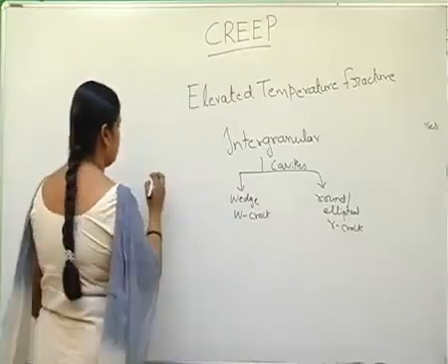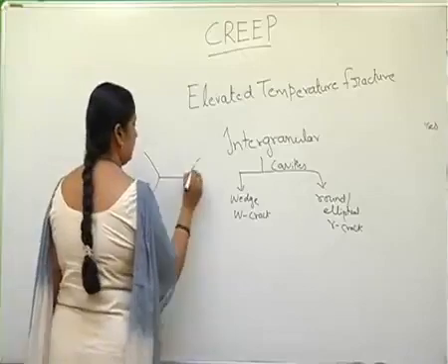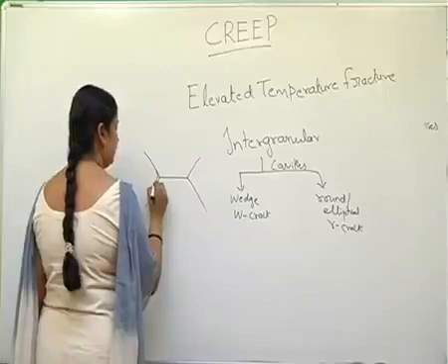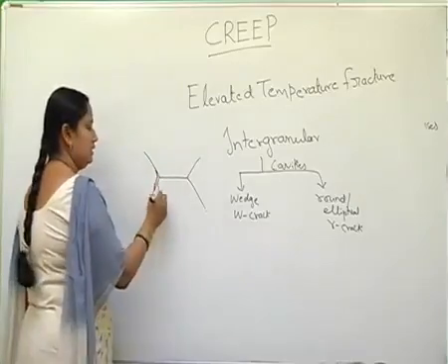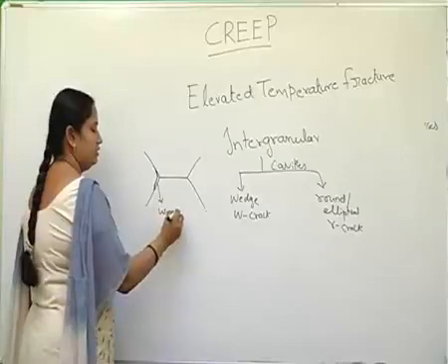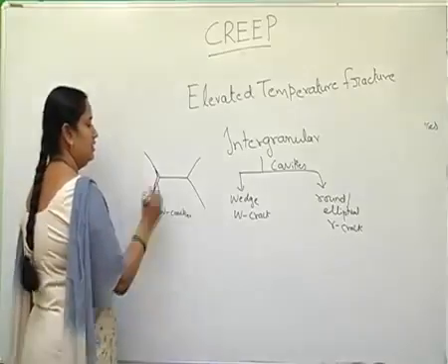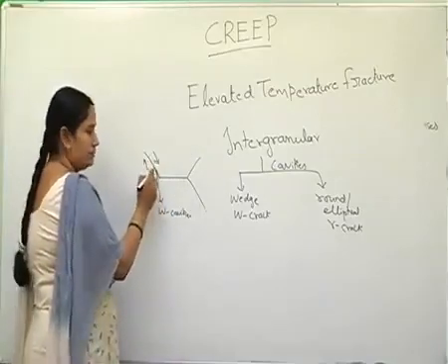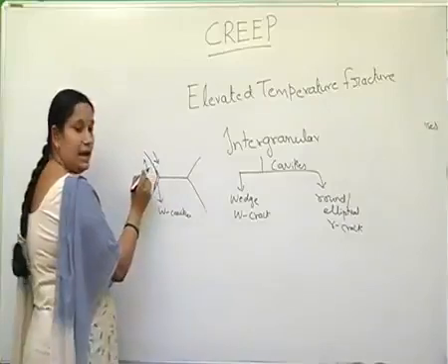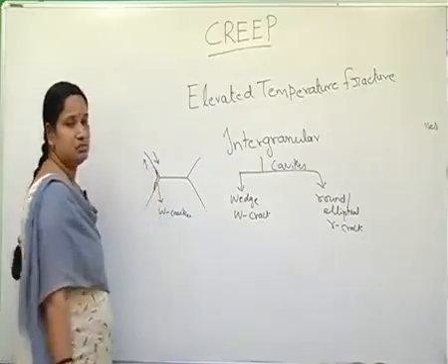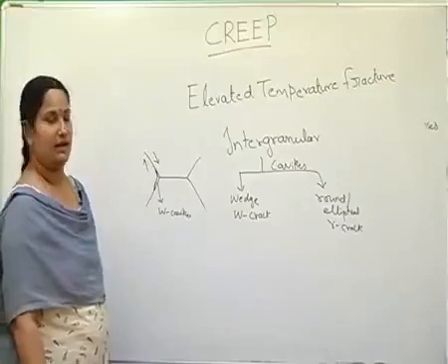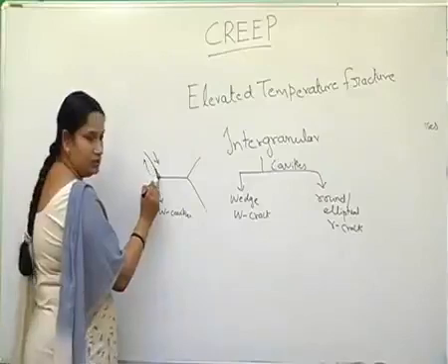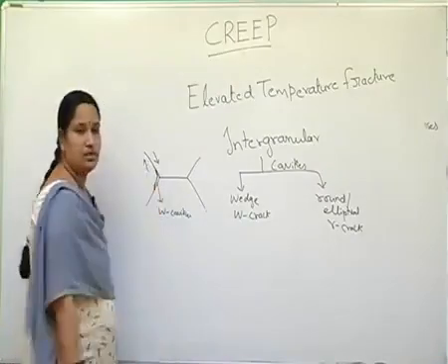Triple points are the points at which three grain boundaries meet. From this figure it can be clearly understood that this is the W type of cracking. This is the W type cavity, wedge cracking, which forms along the grain boundaries aligned in shear. This takes place during grain boundary sliding, and it occurs at triple points, where three grain boundaries meet.